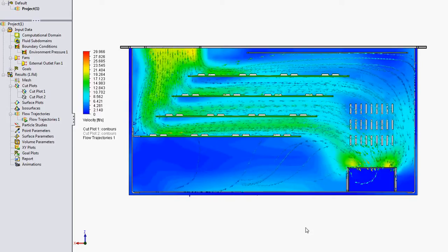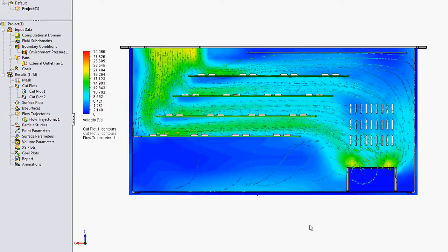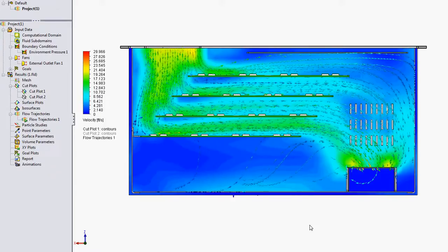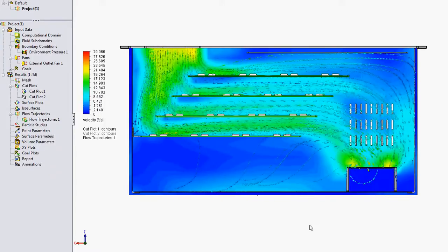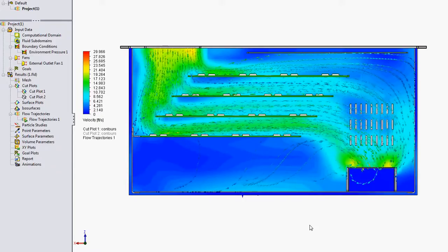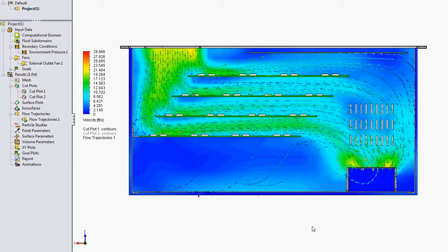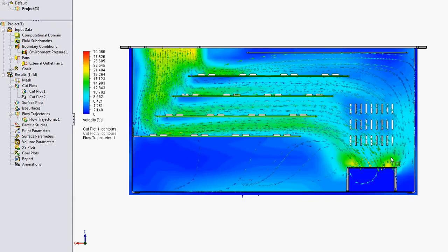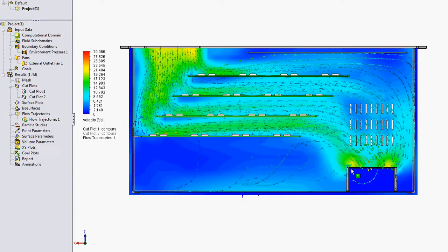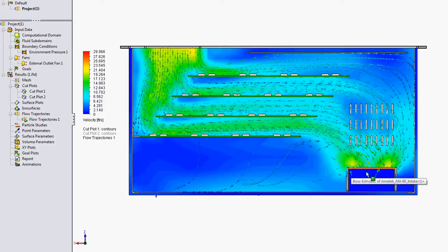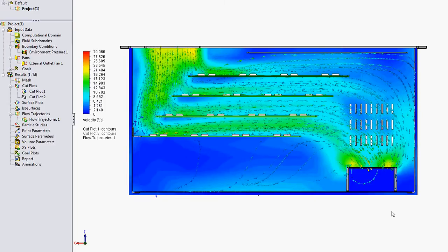Okay, so basically, this just gives you an idea for the flow. What we would do is apply heat loads and perform a component junction temperature and derating analysis. If there's sufficient margin, I'd probably look initially at reducing the size of this heat sink if possible, maybe offsetting it just a little bit more forward, just to make sure that there's no boundary effects or back pressure condition along the lower edge of the fan where this resides.